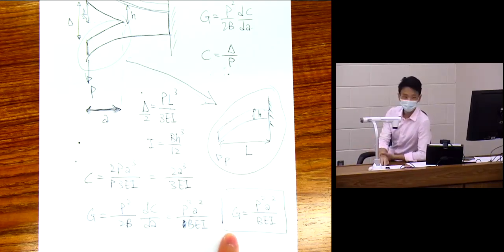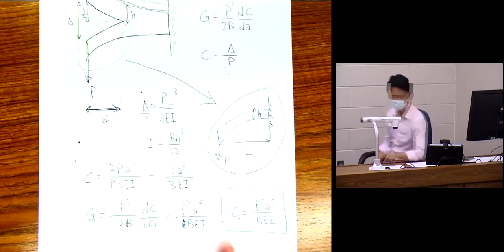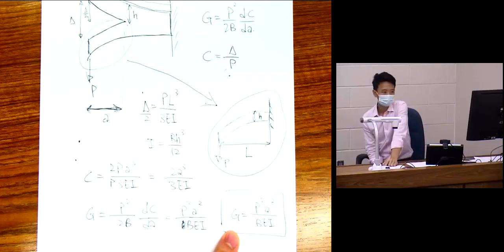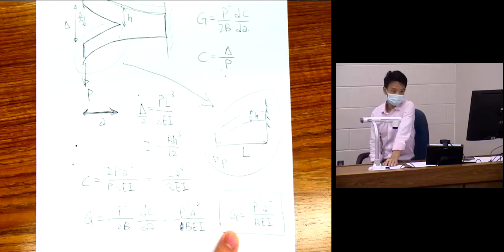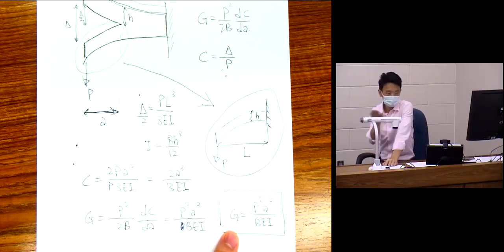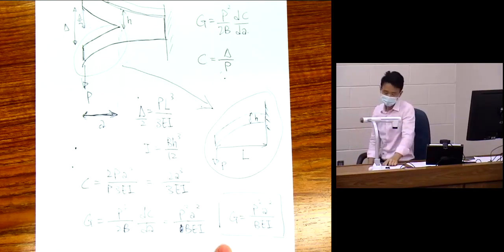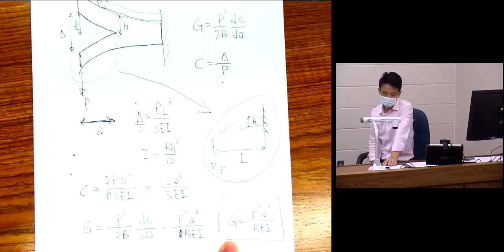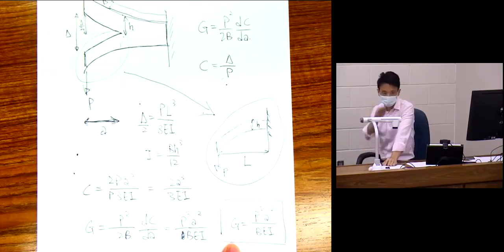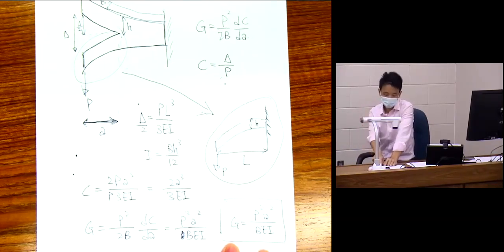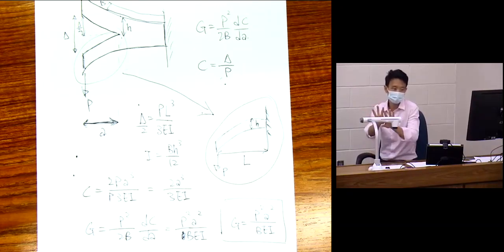And then calculate G. Some finite element analysis directly calculates this for you. We're going to use Abaqus. Abaqus does that. You have to define where your crack is. You can have a very complex structure, then you define your crack, and it calculates this exactly for you based on the stress field computed.